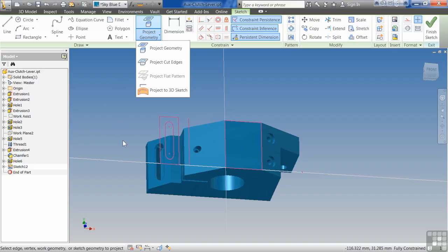It unfolds the part so that you'll know what it'll look like in the flat, so you can modify it in the folded model. And then we have project a 3D sketch. This is very important when you're doing your lofts and your sweeps, anything where you need to have some kind of complex 3D sketch. We probably won't get a whole lot into 3D sketching, but we will touch on it a little bit when we get into sweeps and things like that.